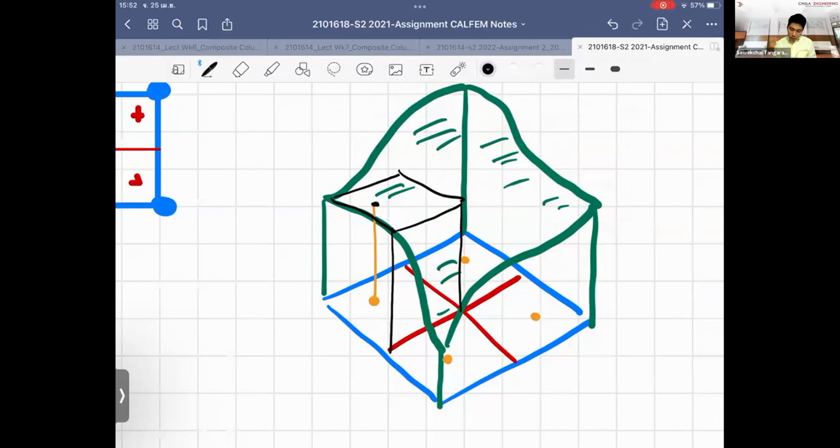And the stress value that they take comes from the Gauss point. So you approximate the stress, not over the whole surface, but you discretize the whole surface by using the information of the fixed stress at the Gauss point. Similarly, we have another stress value at the next Gauss point, so it might project the stress value up to this level.